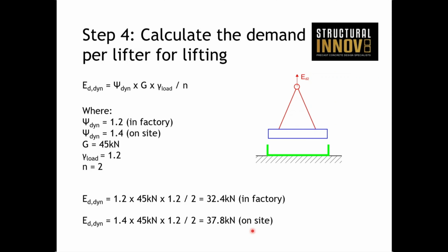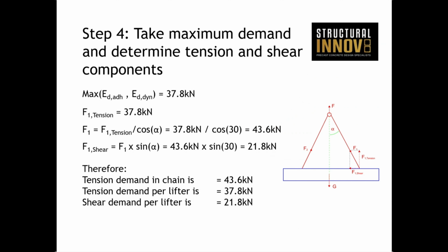So for simplicity, and because we're going to be using these spherical head lifters to lift off the truck on site, we're going to just carry forward this number here for now. So it's the worst case that those spherical head lifters are going to experience, and we're going to carry that forward, just to simplify it a little bit anyway, and we'll see if it will work with those conservative assumptions. If it doesn't work, we can come back and refine our result.